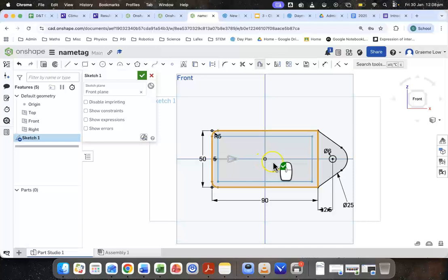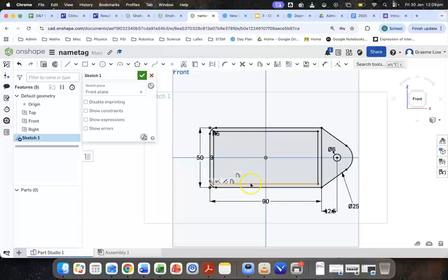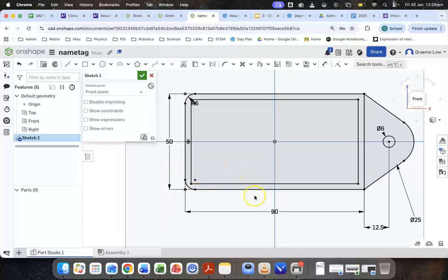So that's the offset. Now, the information you need is the offset number. That's basically how far it is from the outside to the inside of that border. At the moment, it's 5 millimeters, which is probably a little bit too much, so we might put it back to 3. So that looks pretty good. About the only thing I'd probably change there would be, again, sharp corners. I was kind of hoping the offset might put the curve on the inside as well, but it hasn't for whatever reason. Sometimes it just won't work.